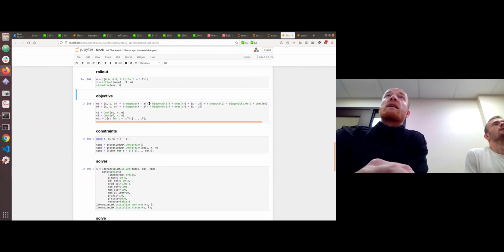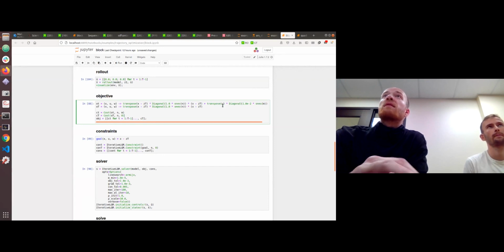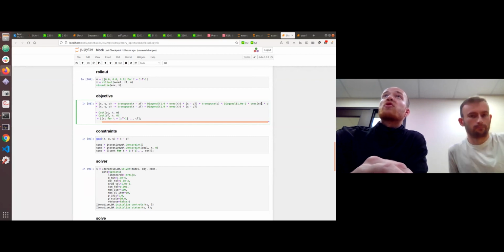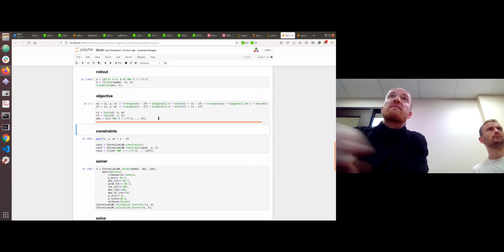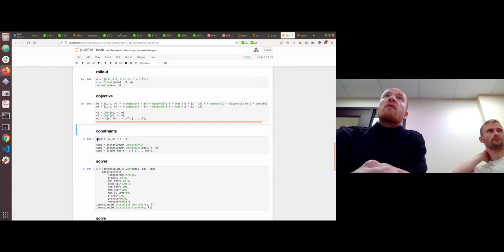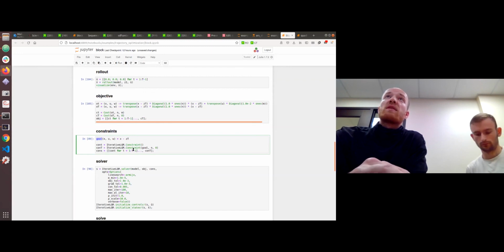We can now define an objective. We define a stage cost, basically just quadratic on deviations from the goal. Then we have quadratic costs on the controls, which are a bit smaller. And then we have a terminal stage cost, which is the same as the stage cost on the states. Here we generate these cost function objects and then generate a trajectory of costs that will form the objective. For the constraints, we define a goal constraint, which is basically that we want the final state to be equal to ZT. Similarly, we define a trajectory of constraints for the optimizer.